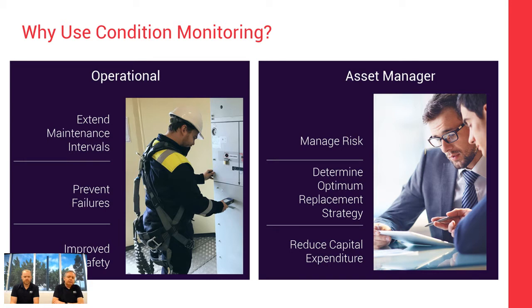At the same time, over the years in the electricity industry, and you see it in process industry, there has often been a case of time-based maintenance where it's been maybe going into the assets a little bit too frequently. So if you're going to start moving towards extending those maintenance intervals, you really need to be in a defendable position. So using condition monitoring can be a way where you can start pushing out maintenance intervals and targeting maintenance where it's needed rather than just on a pure time basis.